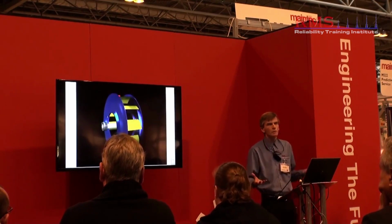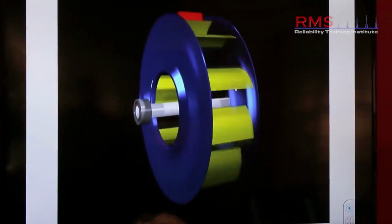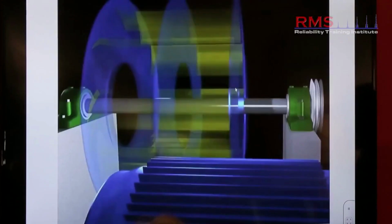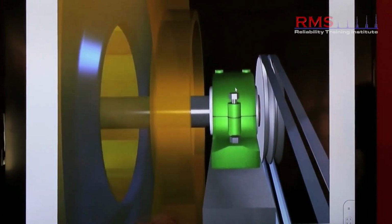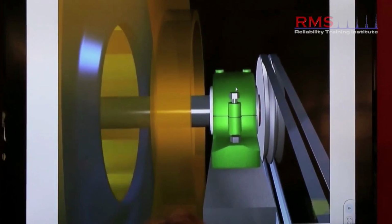Maybe with an imbalance, the forces here are more radial again. The force is radial, but it's more of a motional force. Maybe in this context, the heartbeat would produce another distinct pattern. The shaft's bent produces a particular force. Maybe in this situation, we've got more of a shock event or an impact event. So it's going to disturb the signal in a slightly different way to what we've seen before.